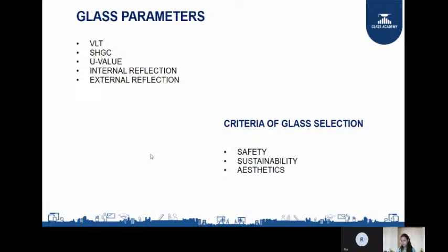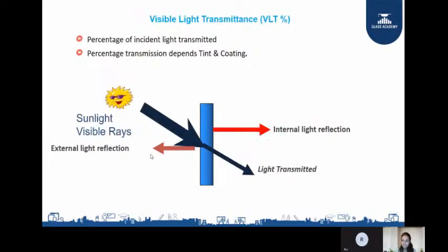Okay. Now we have the fire safety glasses. Generally there are two types of fire safety in the building, passive fire protection and active fire protection. What happens in active fire protection? You put a fire alarm system, or a fire extinguisher or hydrant, or a sprinkler system, or you can call the firefighters, right? But what happens in passive fire protection? Passive fire protection uses a system that does not require any motion or action in order to work.